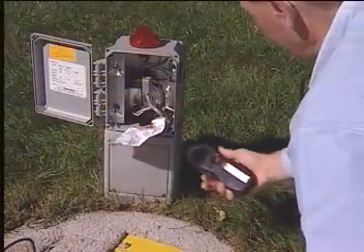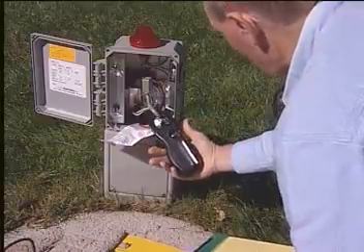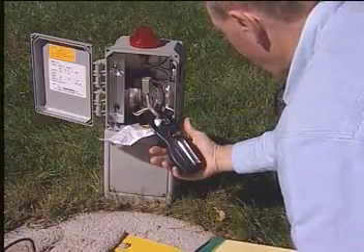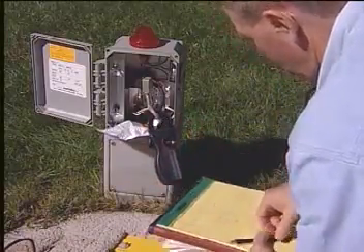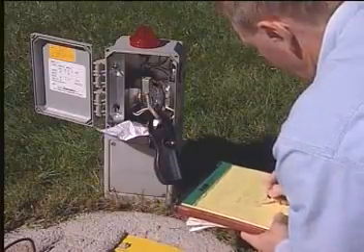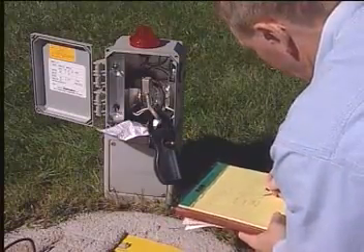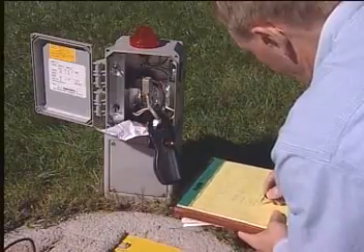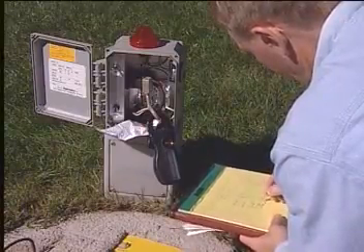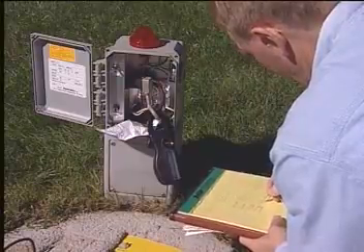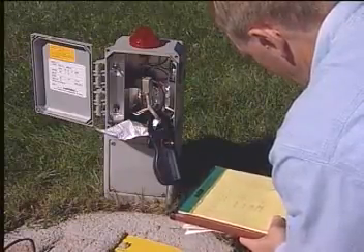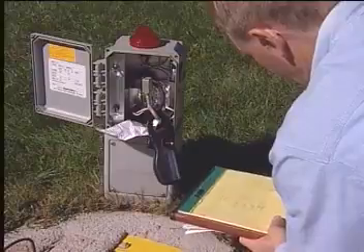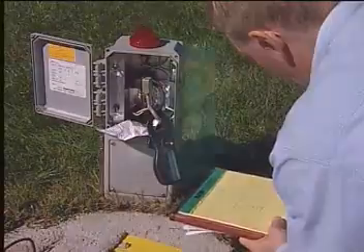A pump in a septic system should be inspected at least once a year, or more frequently if specified by the pump manufacturer or local codes. Systems with control options permit monitoring of the system. By monitoring the amp draw of the pump, length of pumping times, for example, and logging the results, a history of system performance is established and changes in performance can be evaluated.